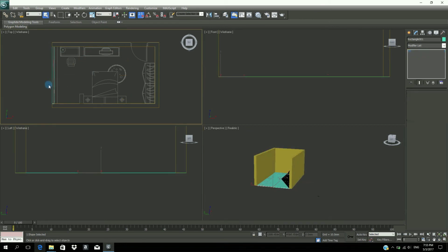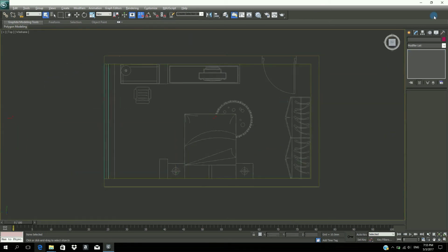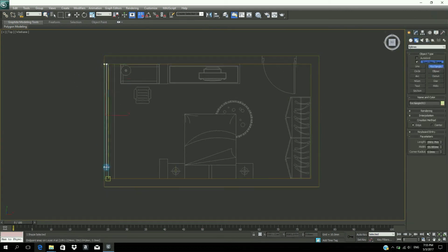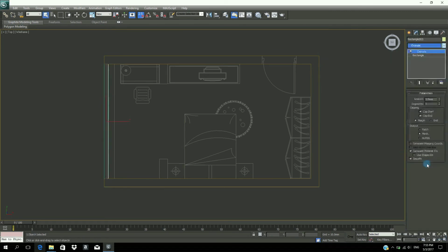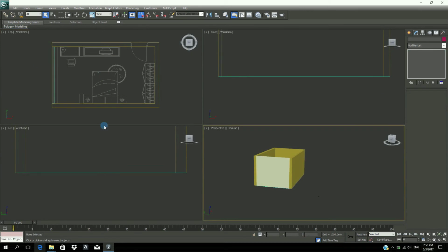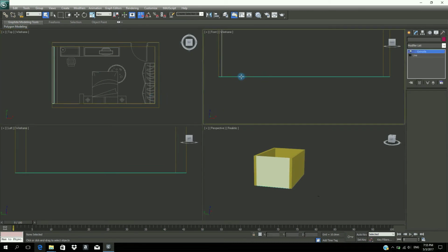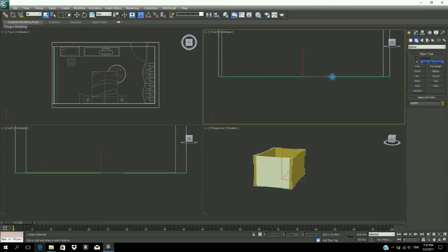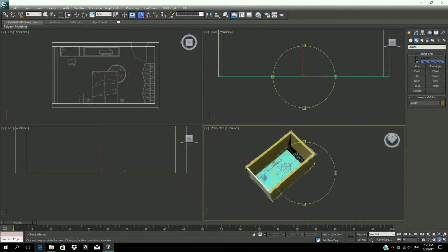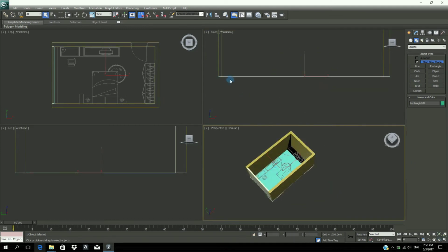We'll make sure that we create a window, that the window is extruded. Just click and drag on the window part, and then we'll go to extrude, and we're going to choose 3 meters. And then we'll do the same thing for the ceiling. We can choose the flooring. If it's hard to click on, then we can just go on the perspective view and press on it.